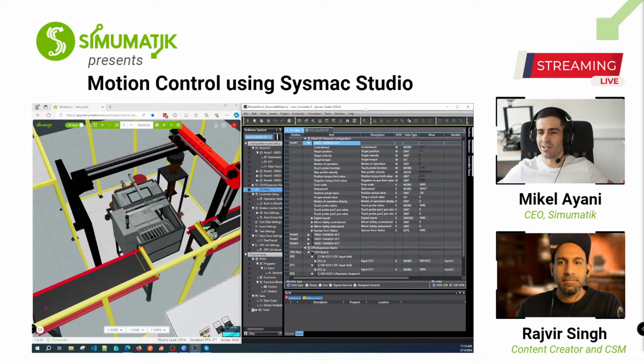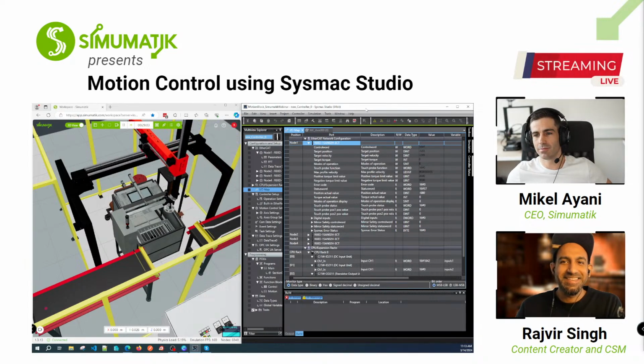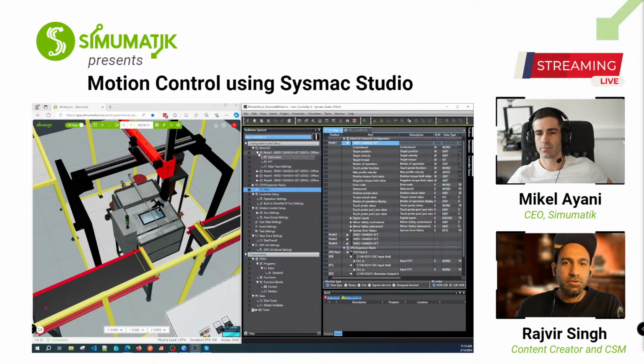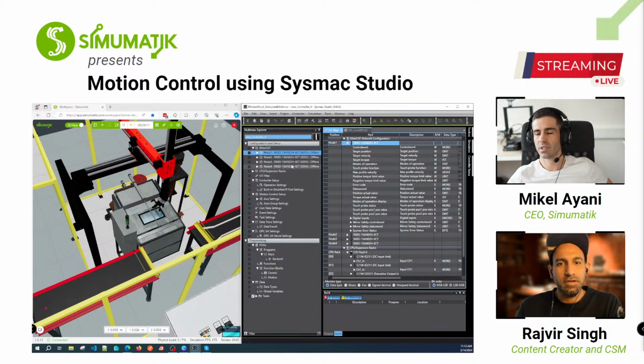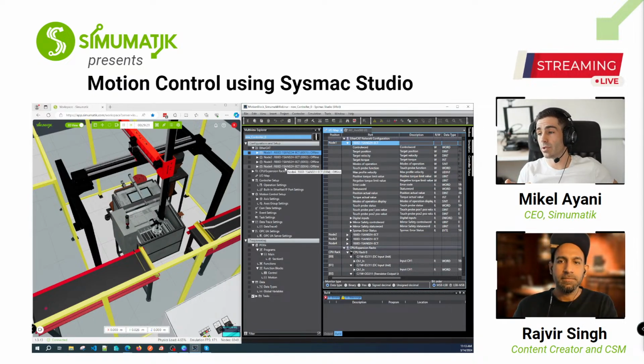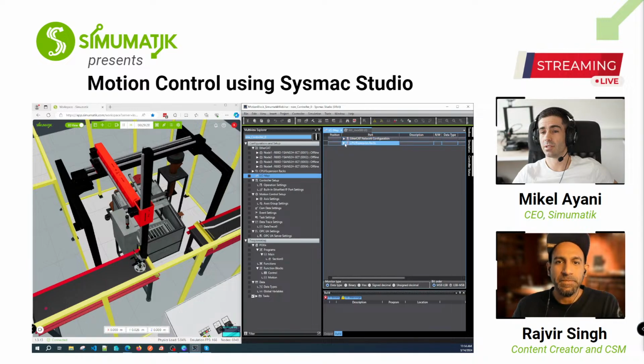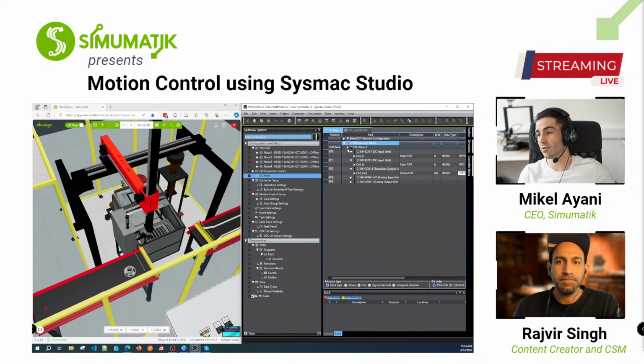But it looks like the EtherCAT is being simulated. It also works with soft or virtual drives. But I spoke to the Omron guys, and they said no, you can use real hardware in the configuration for the IO access. And this is cool, because as we have seen with the IO mapping, we have the hardware configuration that is going to be the same as in the real system.